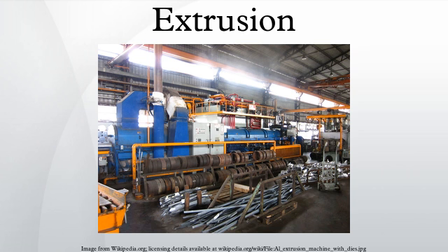Another breakthrough in lubrication is the use of phosphate coatings. With this process, in conjunction with glass lubrication, steel can be cold extruded. The phosphate coat absorbs the liquid glass to offer even better lubricating properties.